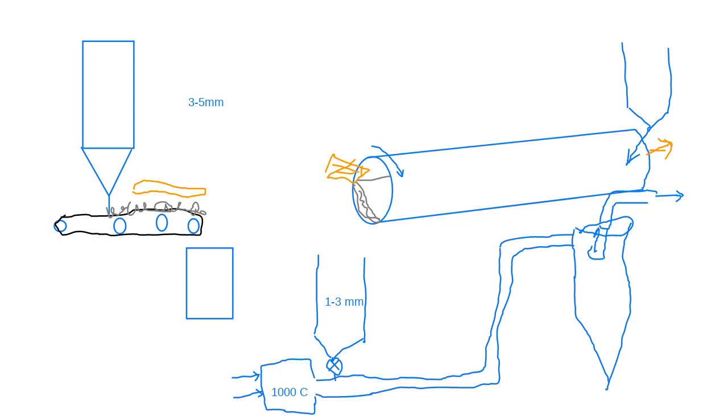And then in a vertical, of course, that's easy enough, as long as the velocity of the gas is higher than the terminal velocity of any of the particles. So the terminal velocity of your 3 millimeter particles will be, let's say that terminal velocity is 18 meters per second.